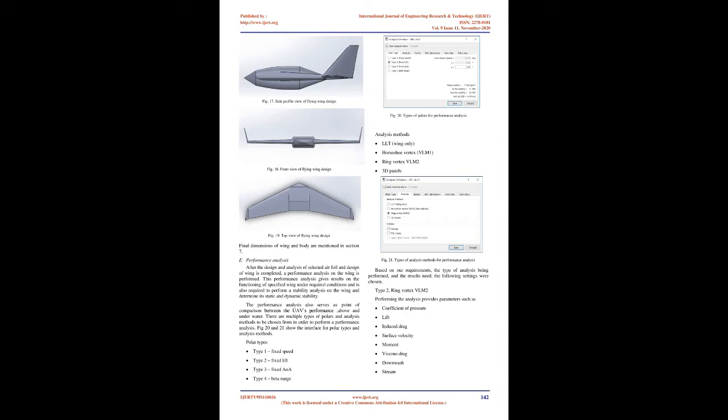V. Design. A. Design of airfoil. Airfoil selection is done for a flying wing, which is essentially a tailless airplane. Horizontal stabilizers are absent in such airplanes. This makes them more susceptible to instability during takeoff and landing due to factors like wind gusts. Airfoils in conventional airplanes produce a pitching moment, Cm, or a nose-down effect. For a tailless airplane, such airfoils may make it unstable as there is no horizontal stabilizer to counter this effect.